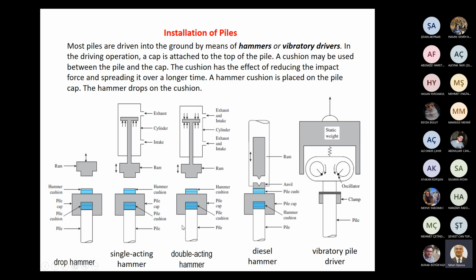And this vibration is transferred to the pile. So vibration on the pile eliminates friction between soil and the pile material, so it makes driving easy.